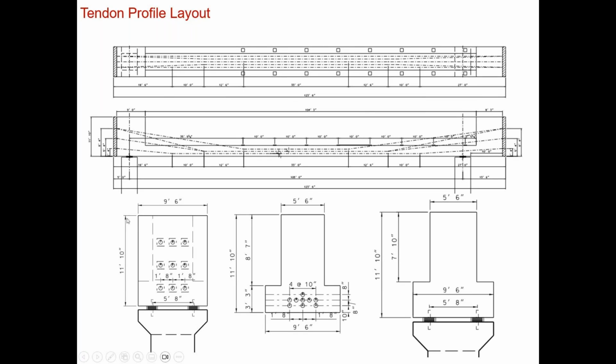This basically came from previous experience, came from the site constraints mainly. So what depths you can use here in the bend and still maintain sufficient vertical clearance for the rail. And not only sufficient vertical clearance for the rail, you also want to make sure that if you end up putting false work and form work and casting this bend, you still have enough overhead to put this false work member underneath the bend section and cast it while not affecting the vertical clearance for the rails, which is very challenging.